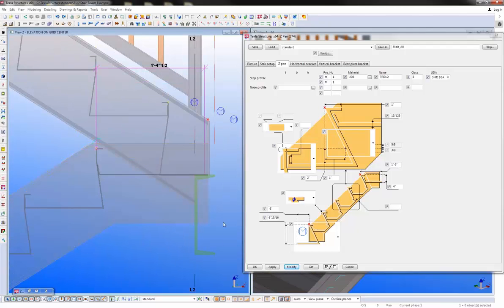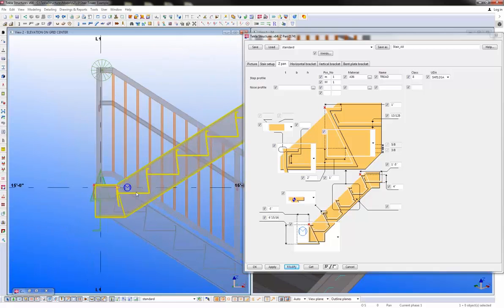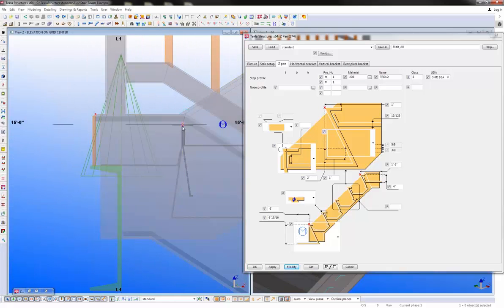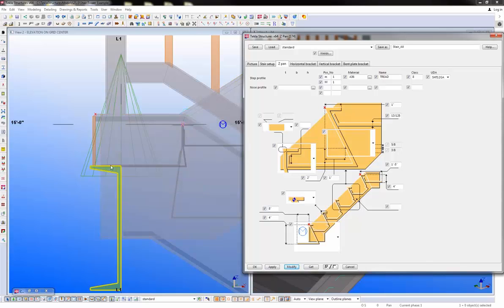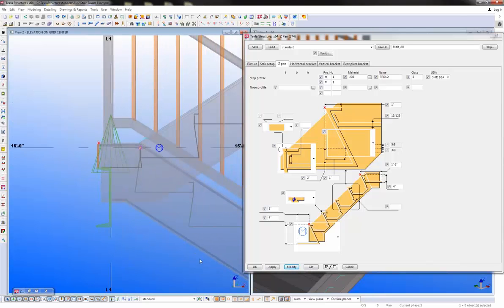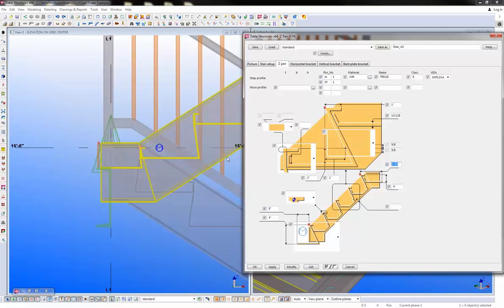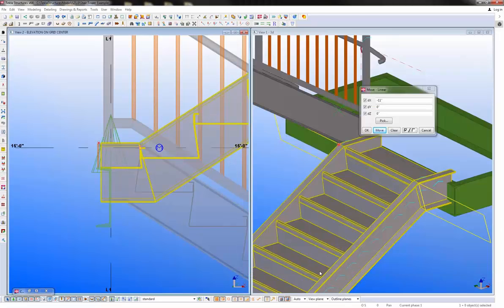And then I'll finish this off in a moment, but first I want to come down here and adjust this bottom pan. This is still being dimensioned out as if it were coming down to a concrete floor. So really all I need to do is set its depth, make sure it only comes down about 4 inches for this concrete decking. And then I want it to turn out, this was at 8 inches, so I'll set the same thing, 8 inches. And now my pan's going to kick out and rest on top of that landing beam. So again, all very visual, very dimension-based. I just come through and adjust the dimensional properties that I want until I get the actual stair layout that I'm looking for.